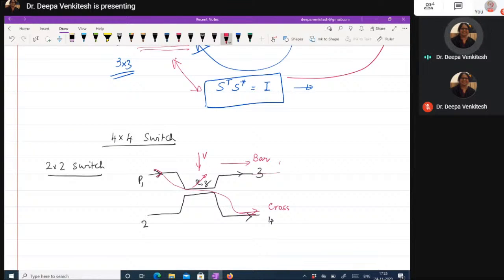That's one way of doing it. Now, the crosstalk suppression ratio of 50 dB is given. So each switch has a crosstalk suppression of 50 dB. What does this mean? When your power is appearing in port 3, the power in port 4 is less than 50 dB corresponding to the power in port 3.